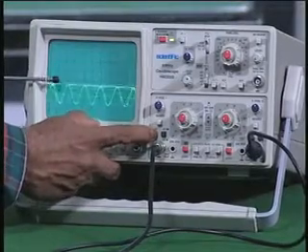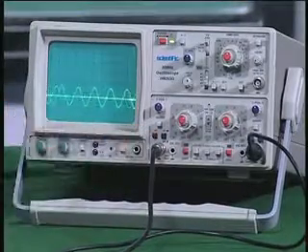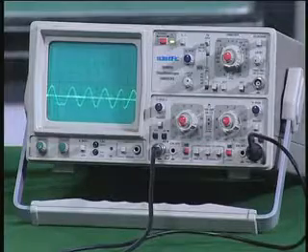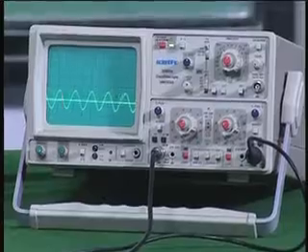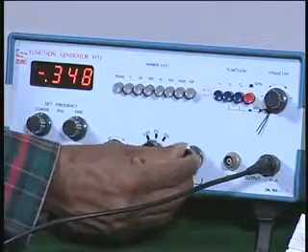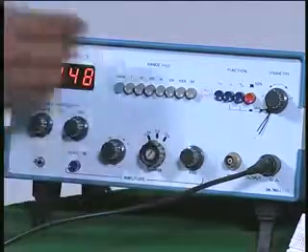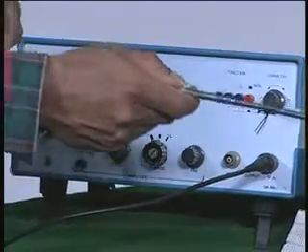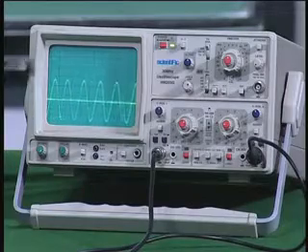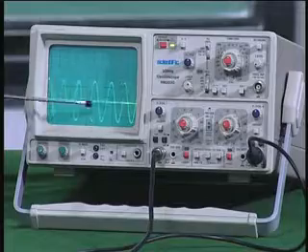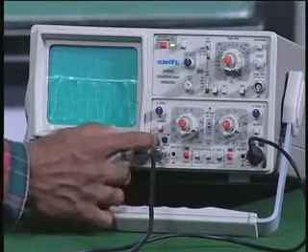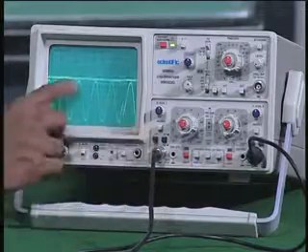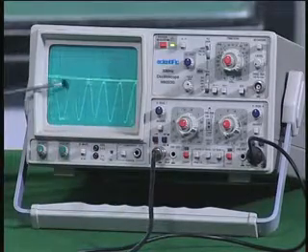So when I put it into DC, it goes to the peak value. So it has been charged to the peak value, and even if I increase the input amplitude by using the function generator, I am going to increase the amplitude now, and you would find at the output in the oscilloscope, again you see a magnified signal, and if I again make it peak detect, you can see it is going up to the corresponding peak now.